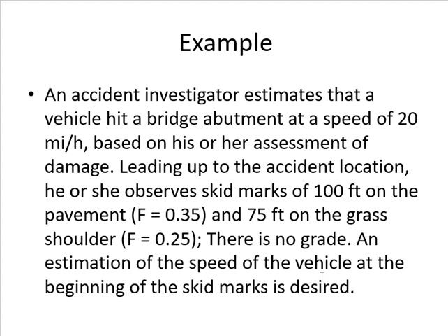on the shoulder. So there is the pavement, the shoulder and the wall. So the driver was trying to brake, moved 100 feet, went to the shoulder, still tried to brake and then to the wall. Now the pavement and shoulders have different surfaces, which is not common. They can be the same surface. So the pavement has a skid resistance of 0.35. The shoulder has a skid resistance of 0.25.